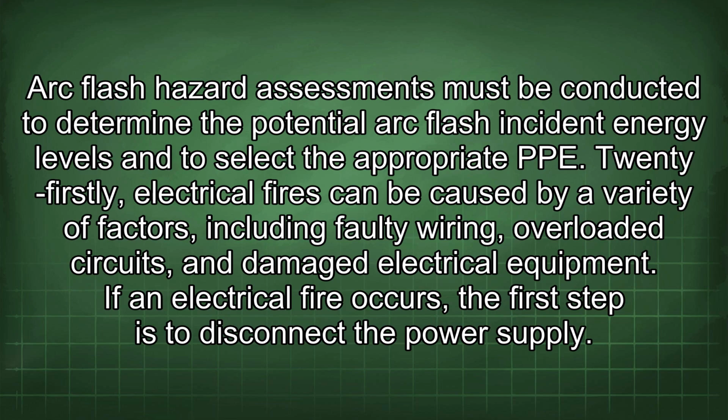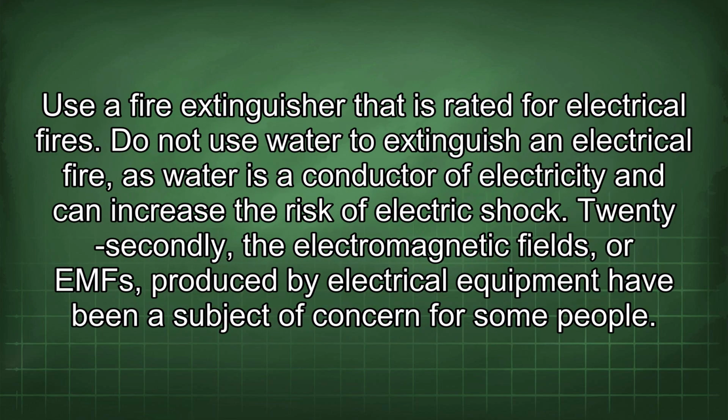Twenty-first, electrical fires can be caused by a variety of factors, including faulty wiring, overloaded circuits, and damaged electrical equipment. If an electrical fire occurs, the first step is to disconnect the power supply. Use a fire extinguisher that is rated for electrical fires. Do not use water to extinguish an electrical fire, as water is a conductor of electricity and can increase the